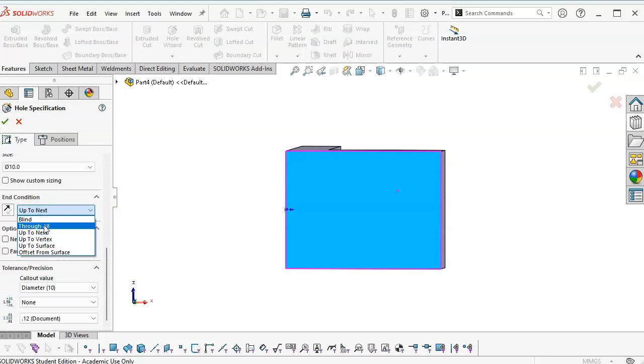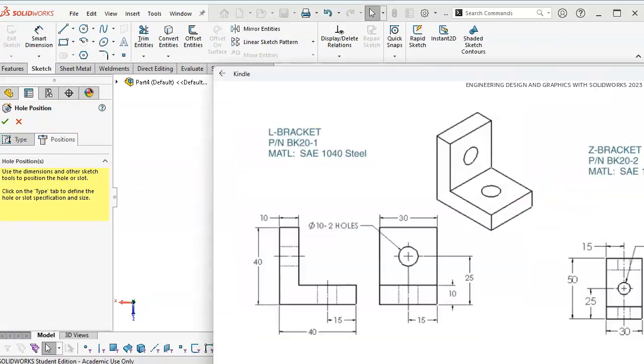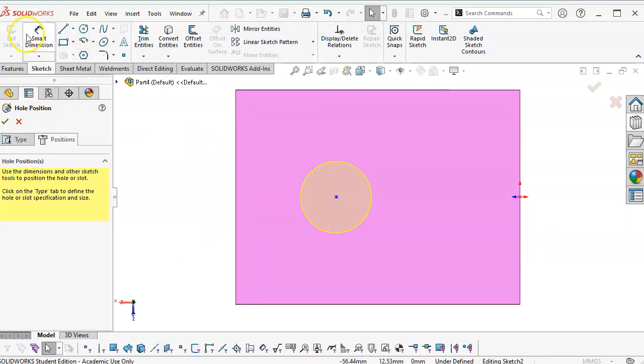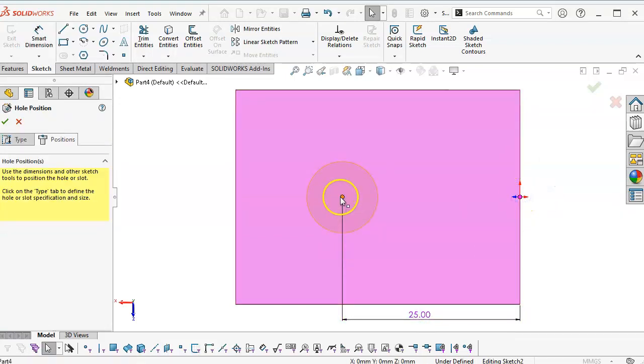Now this one's going to be on the bottom, so maybe I'll go ahead and do through all, because it would, well, no, actually it wouldn't. All right, so we may have to think about generating some of that geometry. So I've just naturally slipped into that parent-child of unlike the save as and modifying the thin feature. When I build that next piece of geometry, it's going to be after the whole wizard, so it's really not going to cut through all anything. So 40 by 40, we have the 25 off the bottom, still centered, and this time I'm not getting the perimeter of the circle, so that doesn't play in. I have to go to the point.